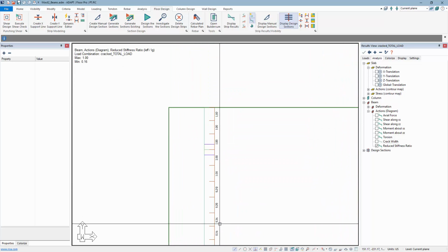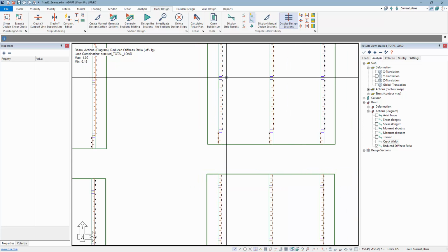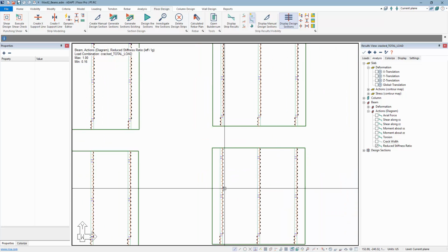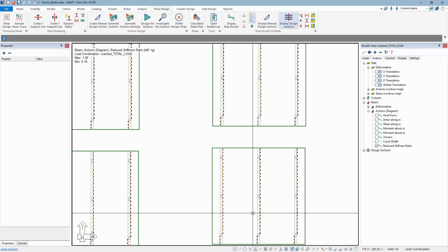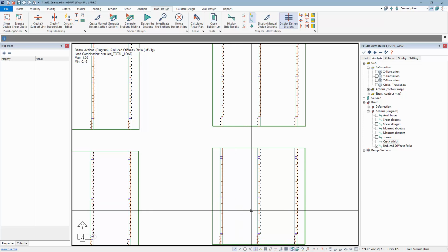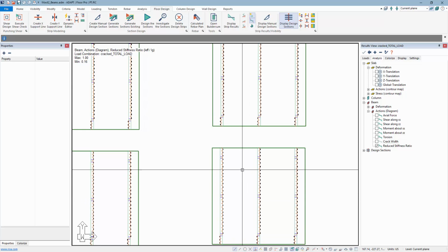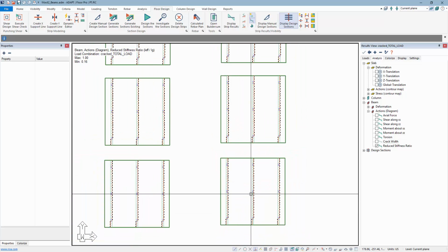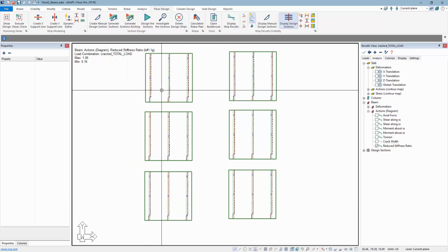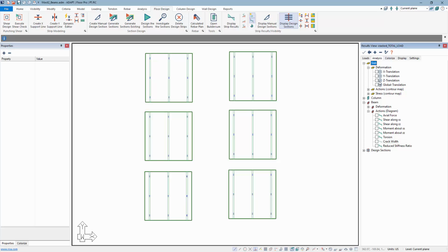Now these two might be the same simply because we're having to add so much reinforcement in this system with the lower modulus that ultimately we get some limitation on the bottom end value of I effective in these two models. But this is how we can show that value for loss of stiffness for beams, and then we can also show that for slabs as well.